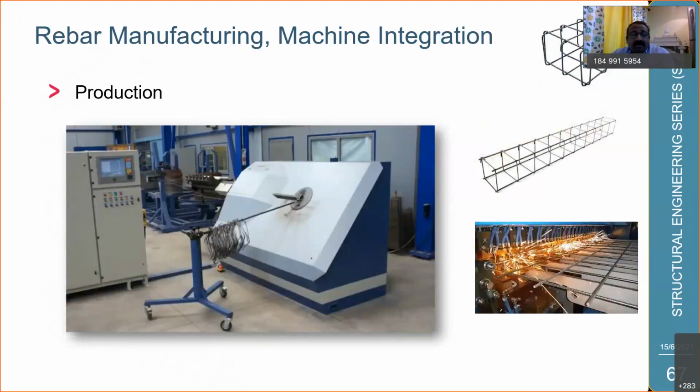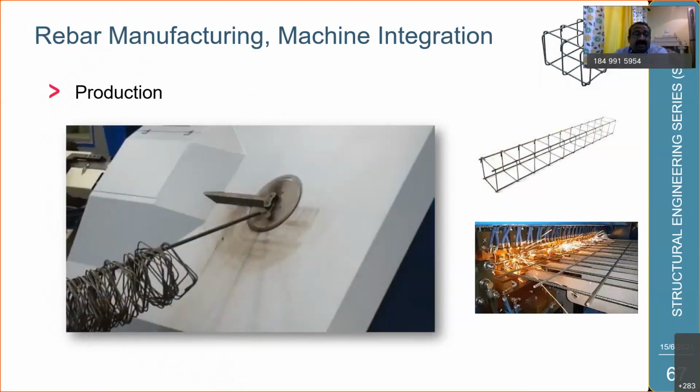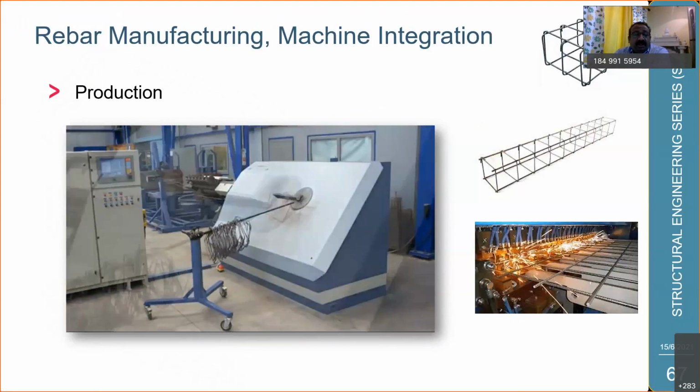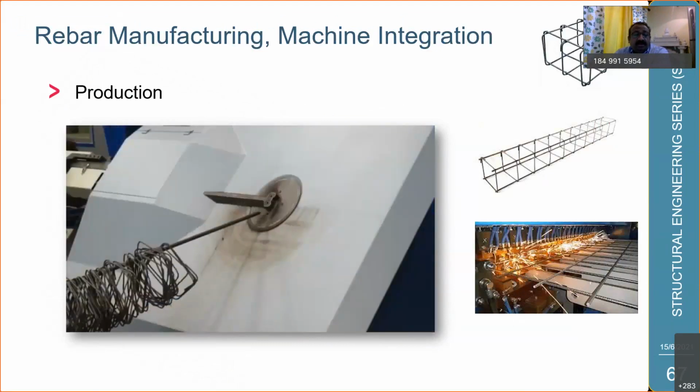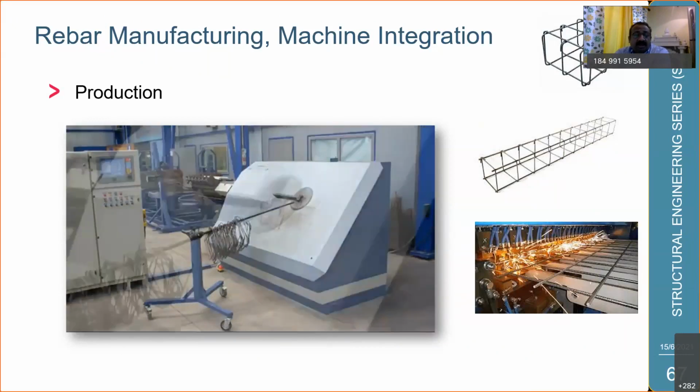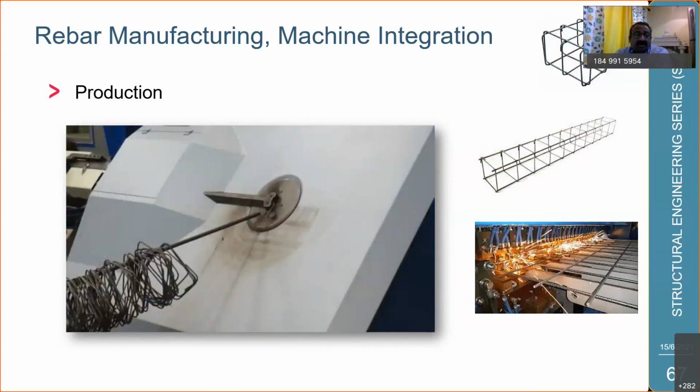And when it comes to the rebar, there are rebar manufacturing and cage suppliers, where the information goes directly with various file formats. And here you can see, when we generate the NC files, it goes to the machine based on the size and the shape. It does cutting, bending, and with proper barcode, the rebar cage with automated welding will be delivered to the construction site.